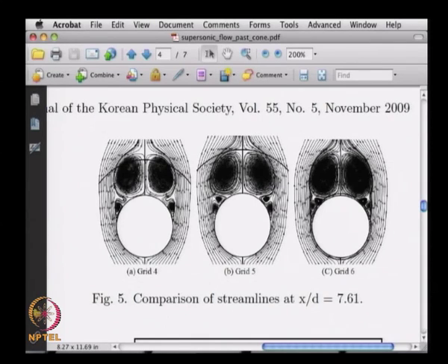Let me just point out a few things. You can see that we have these 2 vortices out here, a large circulation here, 2 here, the same thing. This is much closer together, we have a large congestion, which means we have really dark areas out here. And again, here we have 2 of these vortices which are pretty pronounced, mostly for this grid 6. We can see that in grid 5 as well, but it is not that pronounced, at least the second one is not. So this is how you change your grid to see what sort of solution we are looking at.